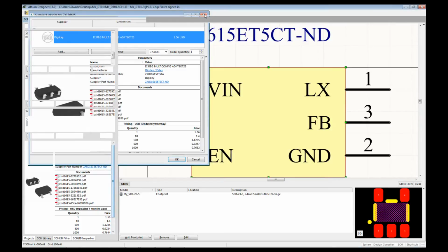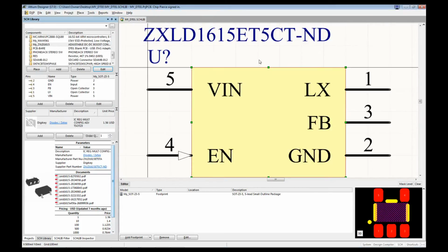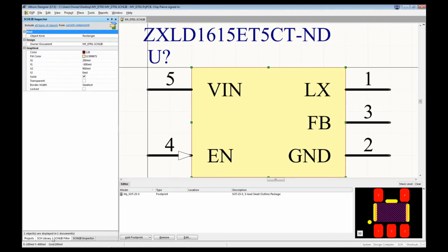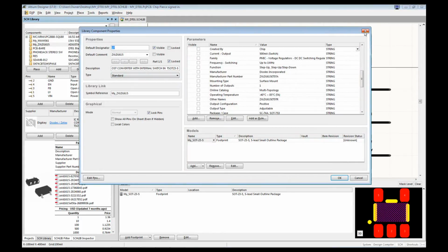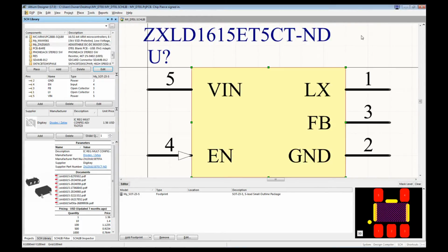Many tips and tricks will be presented throughout the course to give students the information they need that can only be gained through years of experience with the tool. In summary, modules 1 through 4 will teach you how to use the available workspace panels and dialog boxes to help you create new schematic components, and we introduce a process where you place your pins, place your graphics, place the attributes, and use the supplier search panel to automatically add those attributes for you.